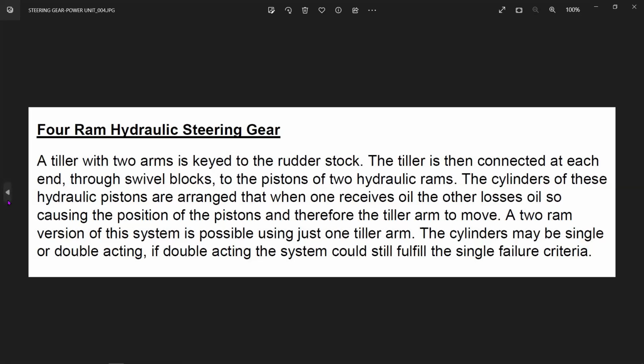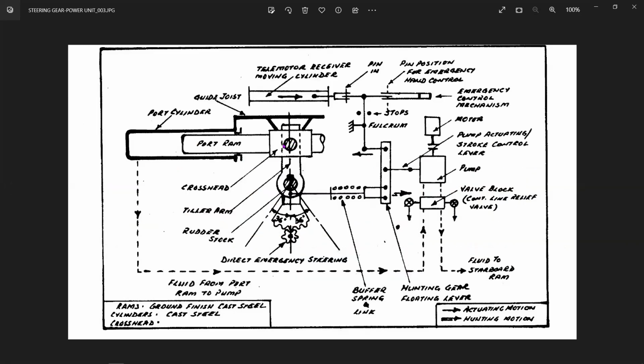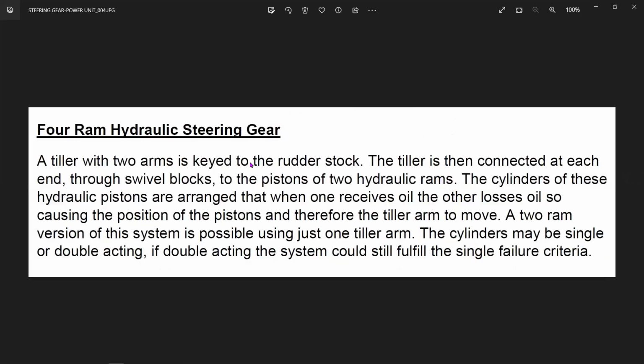Okay. So we are basically talking about this rudder stock arrangement and this entire tiller arm. Either it can be keyed, or as I said, it can also be on a taper with a hydraulic connection, or a taper with a hydraulic connection along with a key. It depends. We will see this when we see the entire thing.